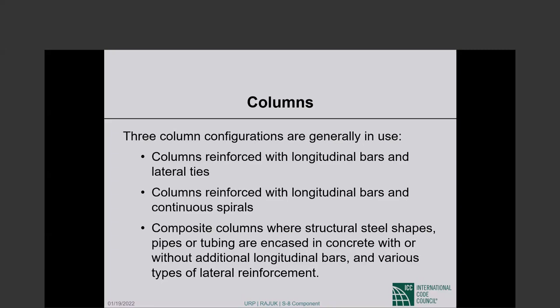Okay, the third, composite columns, where structural steel shapes, pipes, or tubing are encased in concrete with or without additional longitudinal bars and various types of lateral reinforcement. These composite columns, I do not know how common they are. I do not believe they're particularly common. If you want to design them, you need to go to AISC 360, the steel document.